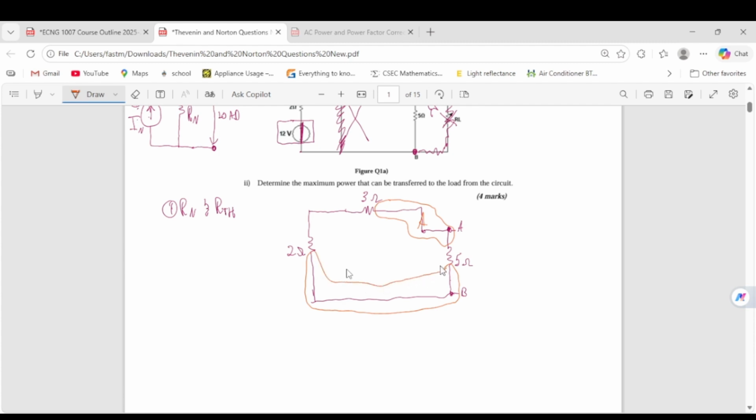If anybody is confused about what a node is, the simplest way to explain a node is basically a bubble that is bounded between components. So this is a component here, the resistor, and this is a component here. If I start here, this is just tracing the wire and following it through, and it's bounded by the components. If I have another component in between, it will break. So for example, this is a component here, and this is a component here. So the bubble will be bounded between these two terminals here. So we know this is B, and we could name this one C.